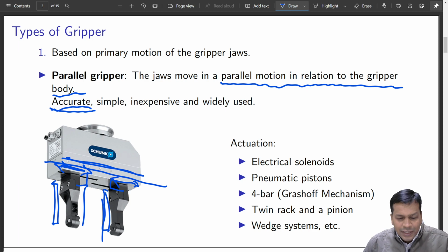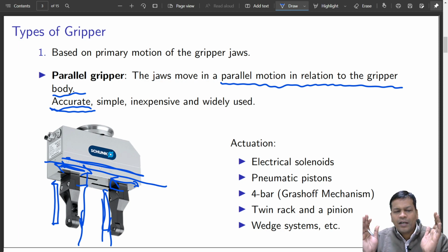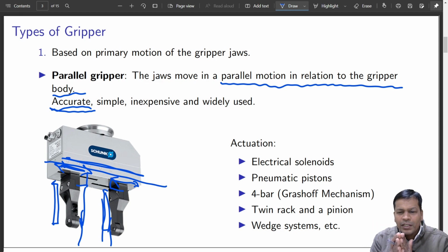Another very prominent type of inaccuracy found in this type of gripper is that it never comes to the same distance every time it closes. It is not a type of backlash, rather it can be inaccuracy in the actuator that drives it.